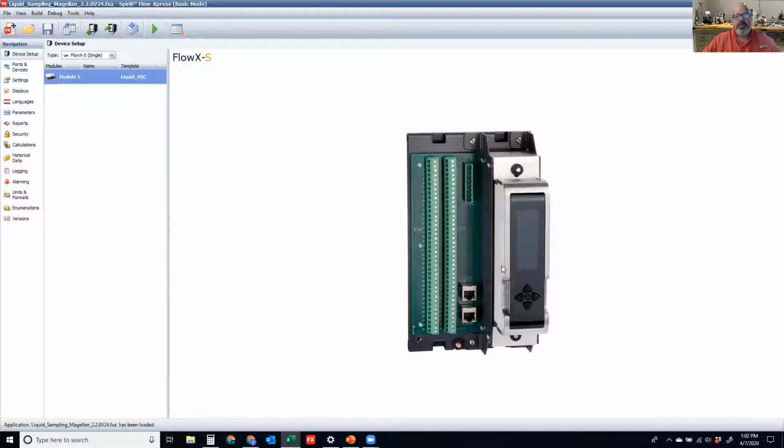So what we've done is we've created an environment where you're able to take a tag and assign it to any type of Modbus data type that you would like, along with a register number for it, and you can create what we call sheets, whole templates of these registers or these tags put into Modbus registers. So another device that speaks Modbus can poll us and we'll respond back.